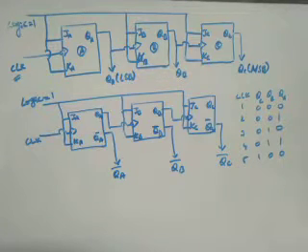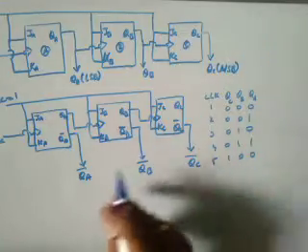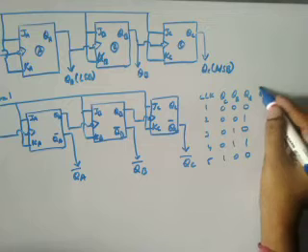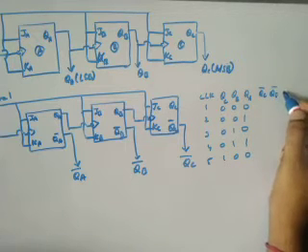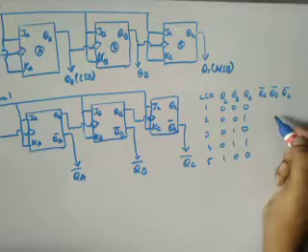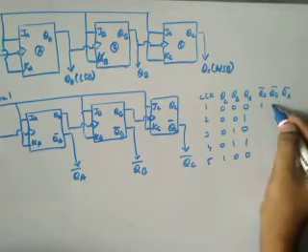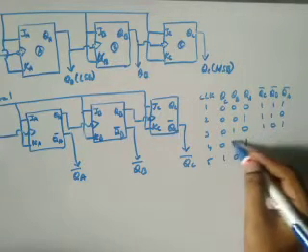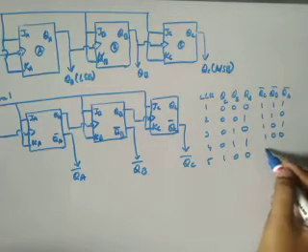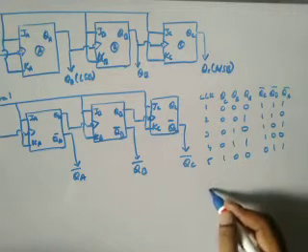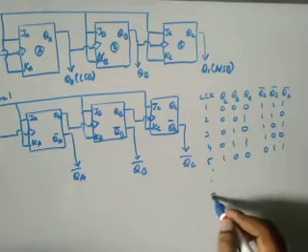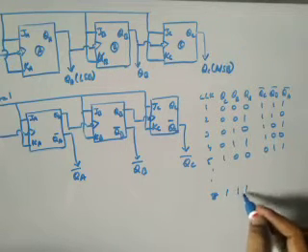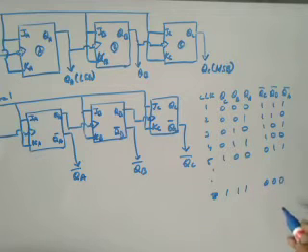But now if you write the values of QC complement, QB complement, QA complement, what will be the values here? Complements: 1 1 1, next it is 1 1 0, next it is 1 0 1, next it is 1 0 0, next it is 0 1 1. Likewise up to 8 values, and the last number will become 0 0 0.